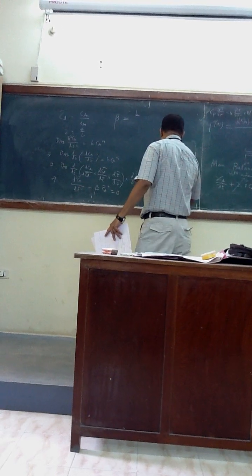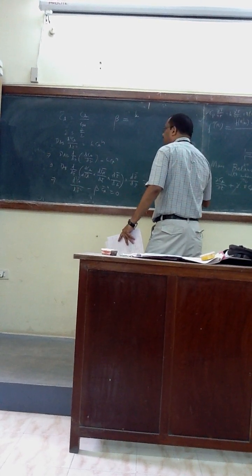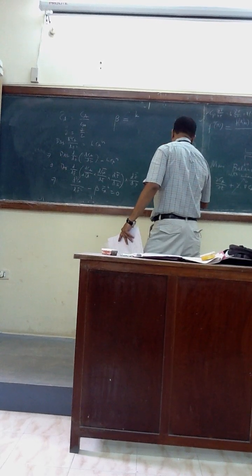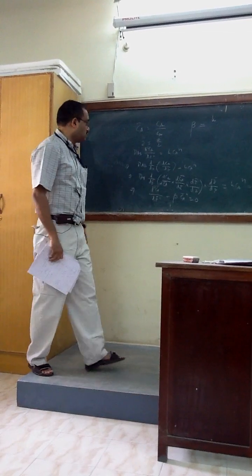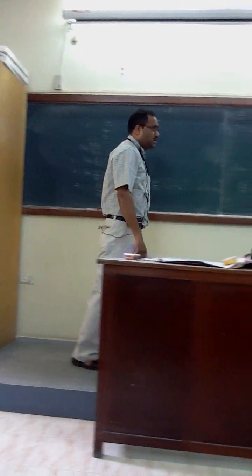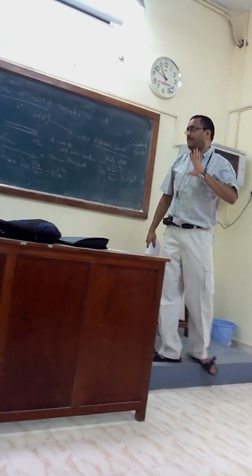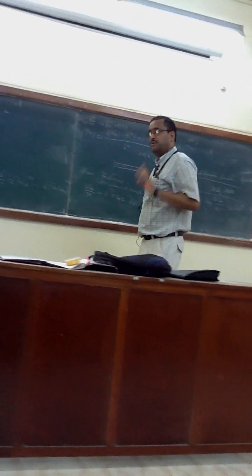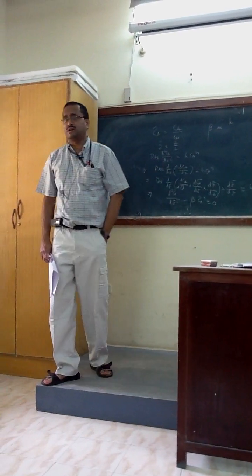Remember that CA to the power n should be substituted by CA bar into CA0 to the power n. Everywhere should be CA bar. There is no dimensional quantity; everywhere is a dimensionless quantity. So in that case, you can say Z bar is varying between 0 to 1, right? In that case, you can apply finite difference peacefully because your step size will be less than 1, and you can apply all these formulas peacefully. Otherwise, the problem.